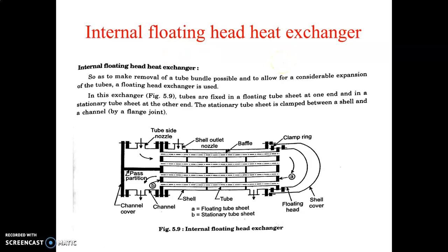So this is the construction of the heat exchanger, and in working you just add the shell side fluid here. It will move in this direction, giving heat to the other fluid flowing through the tube side, and that fluid is removed from this side.